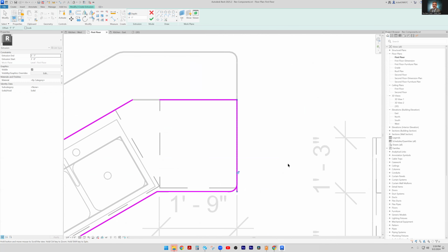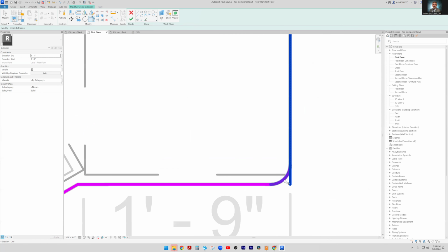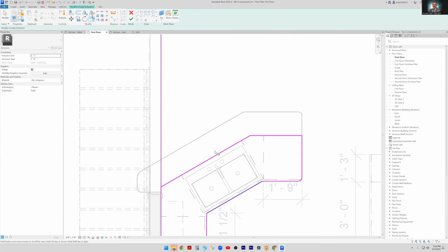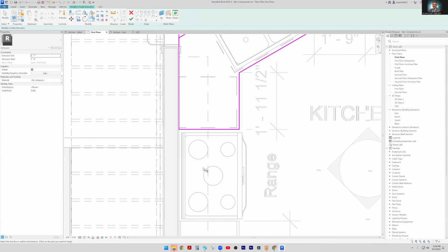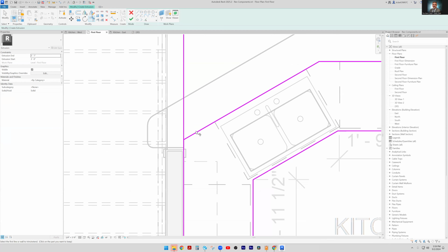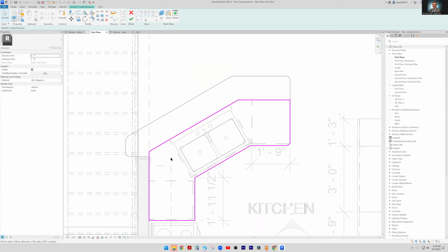All right, so I got some cleanup to do, putting that together and fixing up that corner. So my 90-degree tool, I'll click there, here, and into my circle right there. Now I've got an overlap over here, so I'm gonna clean it up with a click here and here. And then I've got an overlap here. I'm gonna click here and here. The reason why I have to do that is because I can't have crossing lines or openings within my loop.